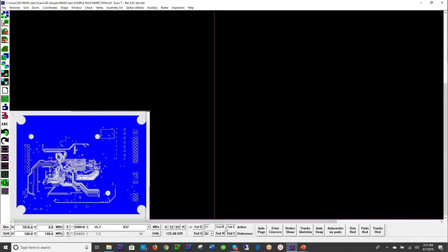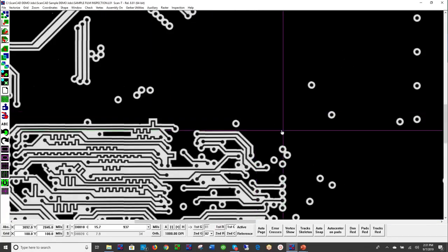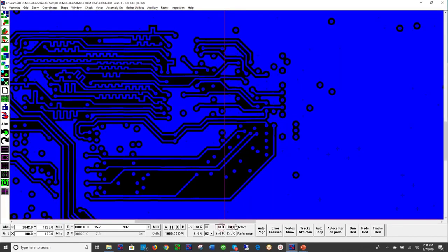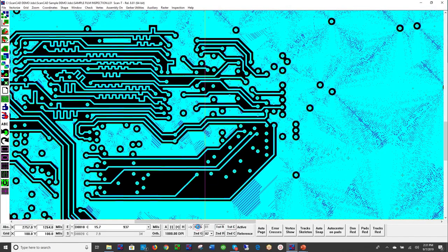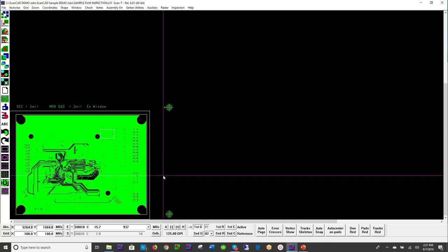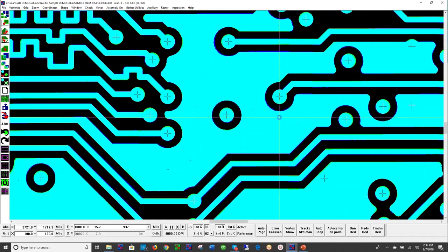So the job is scanned in color. Now, obviously, a film is monochrome anyway. So we'll just color separate on the film. We get this monochrome image. We overlay the CAD data, which is the green data. In fact, if I zoom out, you can even see the targets on the film here. So if I zoom in a bit, we can see we have the actual CAD data of the film. We have the actual film. They all are overlaid. And now we'll perform an inspection.